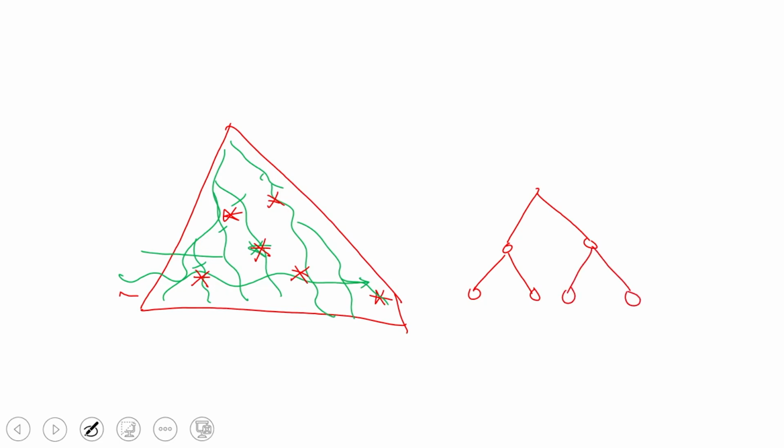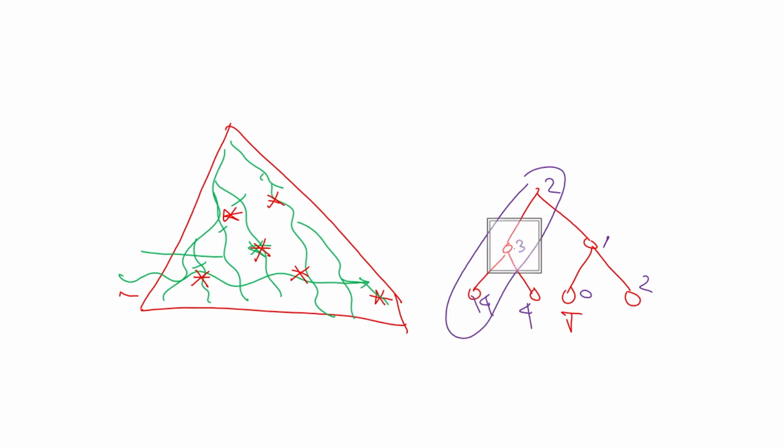One of the heuristics is, if this is the target, you mark it as 0 and this as 1. If this is 1, this is 2, distance wise this is 2, and if this is 2, this is 3, if this is 3, this is 4. So, depending on where you are, let us say you are in this particular path, when you are trying to see which one to flip, you do not want to flip 4, you do not want to flip 3, you of course want to flip 2. The number that is smallest.